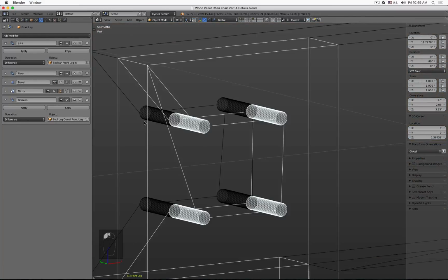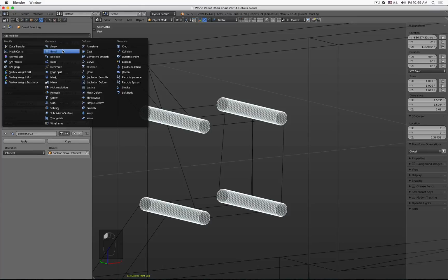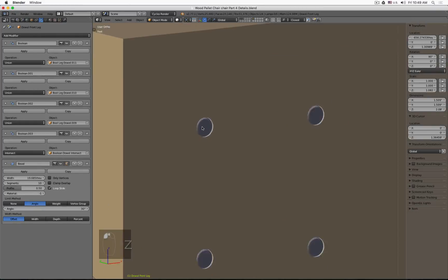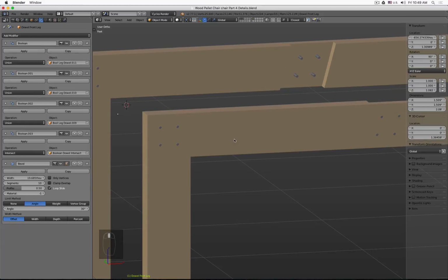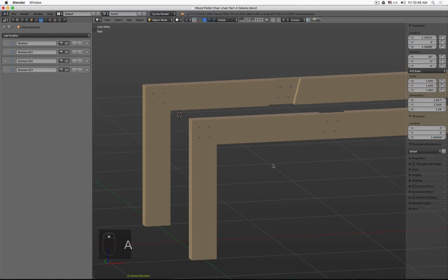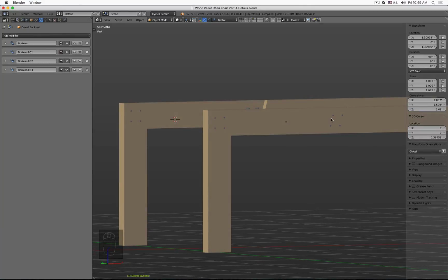And maybe let's go to there. Also here, bevel 0.5 millimeters. We will give this one 10 there, an angle. Okay. So it's up to you to decide if you want to make it look this way or if we rather keep them flush. And to be honest, flush actually will look nicer. So we just force them in, we don't have any gaps. Because now we have kind of like a wood insert. So the dowels we can then use as a visual element.